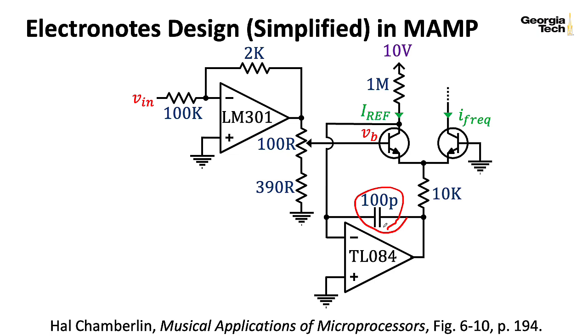And in particular, don't get this mixed up with the integration capacitor that's part of the sawtooth or the triangle core. So, notice that he has a 1 mega ohm resistance here. That's pretty big. He uses a 10 volt source for his reference to create the reference current. That's lower than the much wider voltage range that he's using to, say, power the op amps. So he's generating this using some sort of regulator somewhere. Now, take that 10 volts, divide it by 1,000,000 ohms. That's 10 microamps. So IREF is not that big. But remember, we're multiplying that by a function that's exponential in voltage.